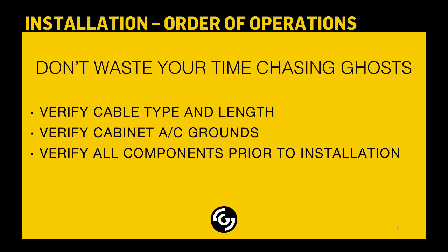And then also verify all the components prior to your installation. It's a real easy thing to do, and it eliminates chasing after things that you wouldn't have to. If you have a contractor that perhaps installed the cable a week or two before the turn on, and maybe there's some other construction going on there, or maybe they just didn't pull the cable well, or tight conduit and ended up breaking the cable somehow. You put the camera up, and all of a sudden you've got an installed system that's not working, and you're not real sure where to start.